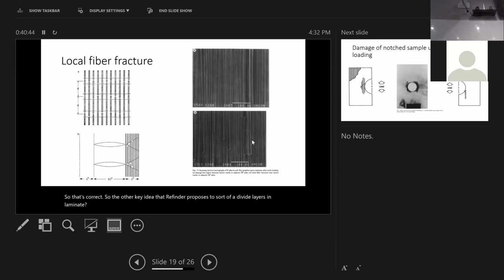two camps. One we call the critical layers. A critical layer is a layer such that when it breaks, the whole laminate is gone. That usually is a layer at 0 degree to the load direction. If the major load is tension in this direction, the fiber at 0 degree aligned with that direction is the critical direction. If the fiber goes, the rest cannot carry the remaining load.